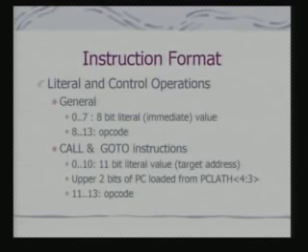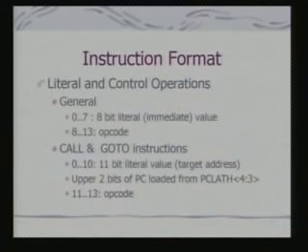Now, these literal values provide for immediate mode addressing, and the data used in the literal value is part of your program memory itself. Interesting to note that your PC has 13 bits and your call and goto instructions have provision for specifying an 11-bit target address value.